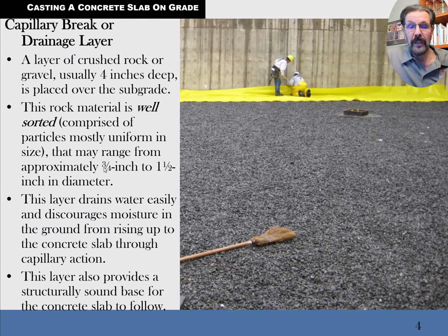Okay, and if you want a slab that's not going to be wet, especially here in Louisiana, you need a well-graded crushed gravel of some sort down underneath. It's free draining, and that you've got a place for that water that does manage to get in there to drain away. And out of that, you end up with getting a solid dry base. And then we put plastic sheeting down. Generally, we're talking about at least a 6 mil thickness.